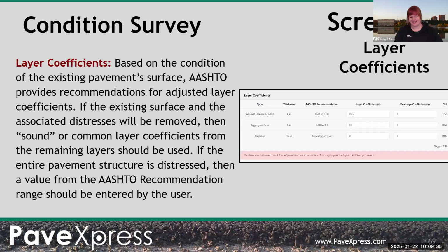Another question is, do you always want to mill through the surface course before paving an overlay? Is that going to be standard all the time? You don't have to, no. It depends on the distress and type of distress you have. That's why it's important to take cores. If you take cores on some of the cracks and see that the crack is propagating from the top down, and maybe it's confined in the first inch, if I just mill off an inch or inch and a half, I'm taking all that crack out of there. So then I'd probably want to do that.